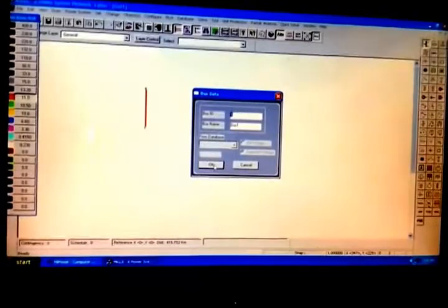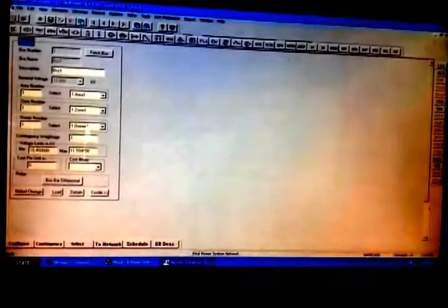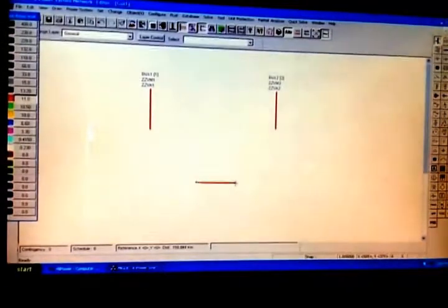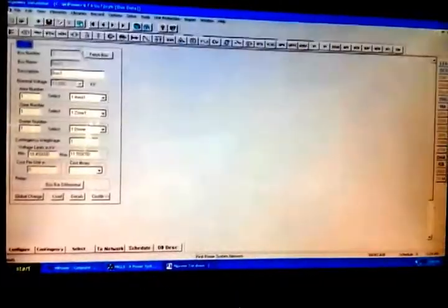Now before we could draw anything, we have to draw the buses. So select the bus and in this select 11 kV. Now just click once and drag it, release this, give OK. Now save this, again draw one more bus, again give OK, save this, draw the third bus and then OK, save it. Now we have drawn the buses, so right click to deselect.